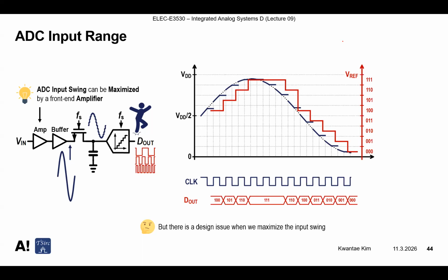And who causes that problem in this circuit? It was part of your CAD exercise. MOS transistor. This guy. Yeah. And which CAD exercise? Do you remember? Yeah, CAD5. Right. So you have verified the DC input range of CAD exercise 5 about this baseline sampling switch. And you probably have seen that there is some flat curve and then it suddenly goes down for the DC input range, right? I'll explain in more detail what is happening in this switch.